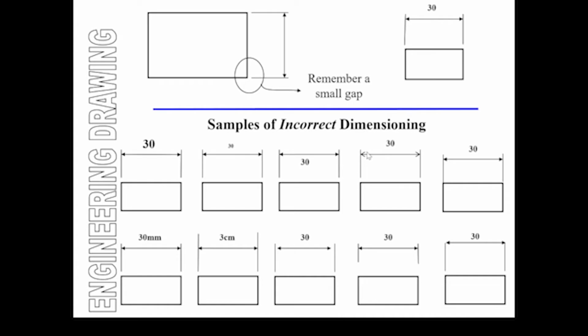Here we have stick arrows, which is clearly frowned upon. It's non-standard. According to British standard, they need to be filled in, long and slender. Here the projector lines are touching our object, which can lead to confusion, hence this is incorrect.